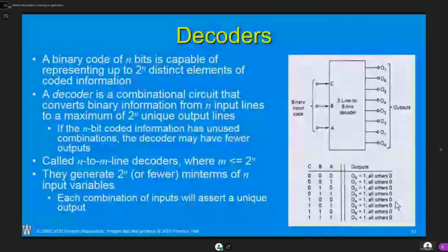Where is the output going to go eventually? It can go to another circuit that enables something else, right? So having that signal of O4, for example, let's say that goes to another circuit that controls another part of my design. This device kind of did that for me. So as long as I put in that pattern, if the number is only 4, then only that circuit's going to turn on, where all the other circuits turn off. It's very useful in this particular area.